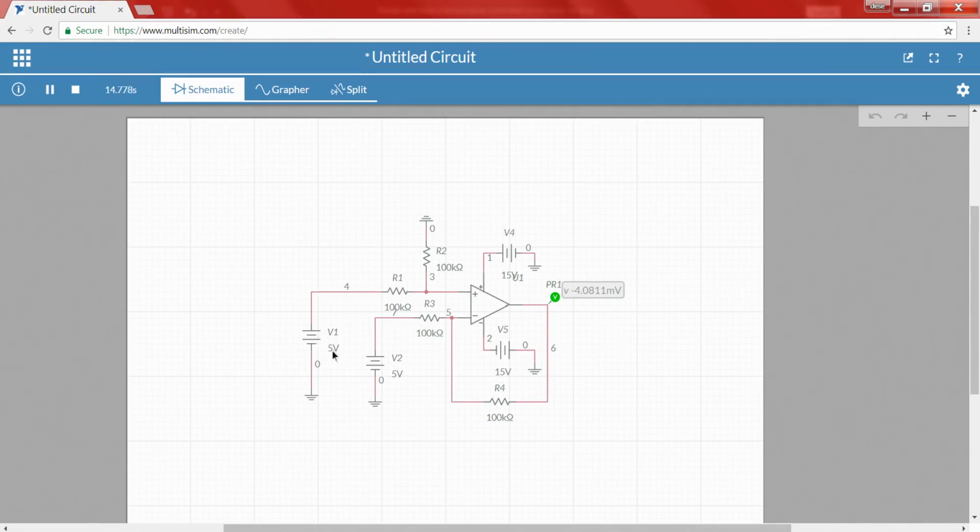So, let me take the value somewhere around 10 volt and this also at 10 volt, should be almost same. Yeah, see, when we see 10 and 10, actually the value should be 0, but we got minus 4.1323 millivolt. Now, let me put everything in a graph and we will put everything in our slide and let us see what we get, what will be the CMRR value, right.